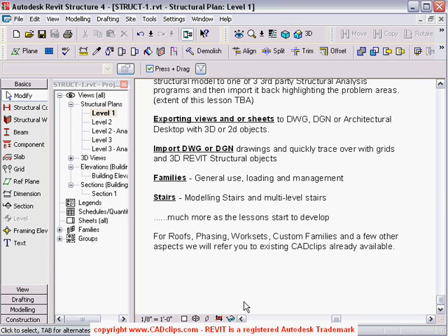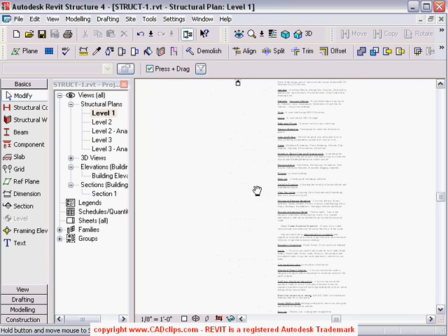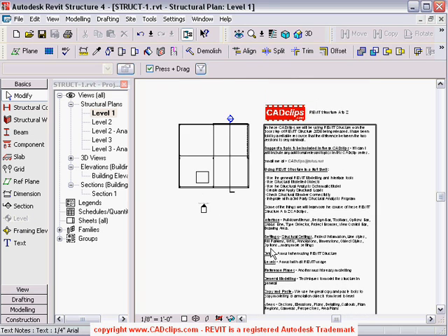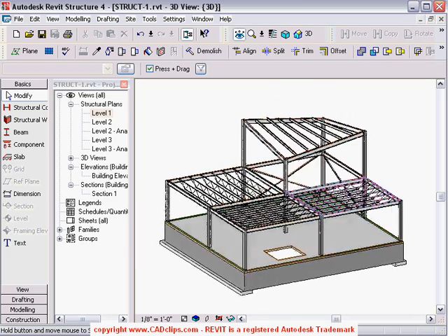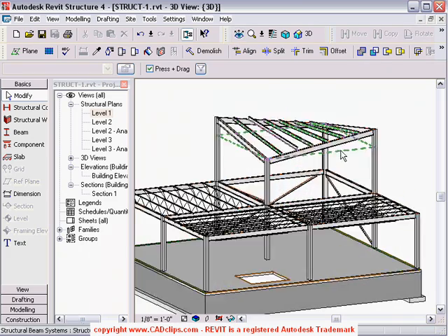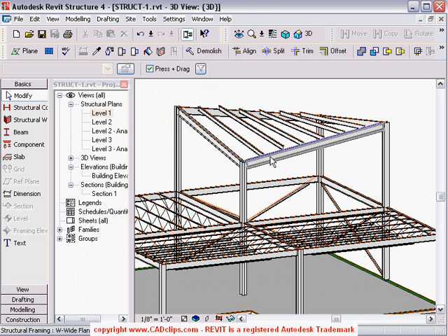So now I've just zoomed in here, and all this is a bunch of text in my Revit model. I'll just have a quick look at my 3D model here, and I've just got a little bit of a teaser here. I'm just demonstrating how you can take a slope beam and tie a beam system. Okay, this is a beam system, all these guys, and tie it to this beam, and then if you slope this beam, the whole beam system will then slope with it.